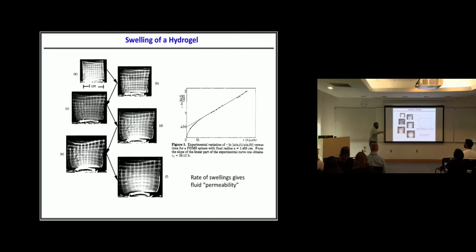Yes. So here, there is also a time scale, but it is not the time scale for the crosslinks to come on and off like the previous case. Here it is associated with the time scale for the fluid to flow. That's what's giving this a time scale. Diffusion is a frictional kind of process. When fluid is flowing in and out, there's dissipation. So this is also a dissipative process having to do with how fast water will flow in and out.